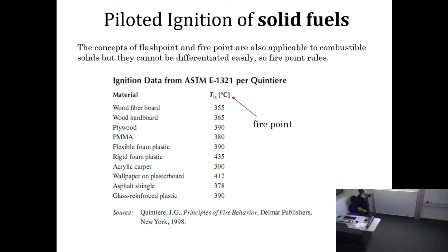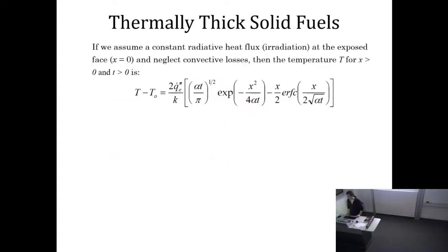You will see, for example, that foam, although it ignites at high temperature, heats up tremendously quickly, because it doesn't have a good thermal diffusivity and doesn't share its heat. That means the surface temperature gets all the heat, and very quickly it reaches not just a temperature, it reaches any temperature. Whereas other polymers might have a lower ignition temperature, but they conduct the heat away quickly in time, so the surface doesn't reach that critical temperature that fast. So the thickness of the material matters significantly, and the heat transfer properties of the material severely modify the flammability properties.